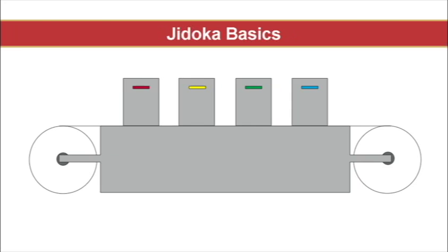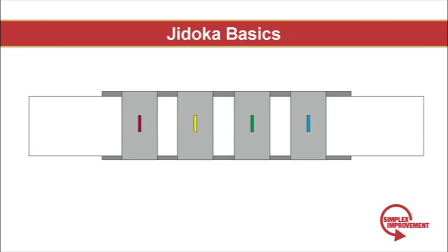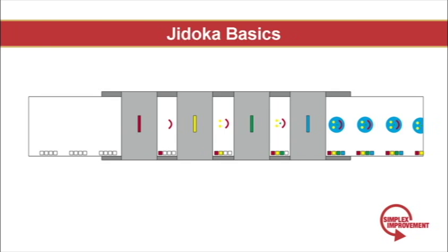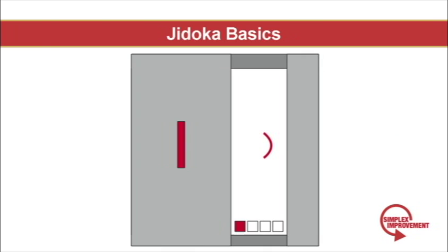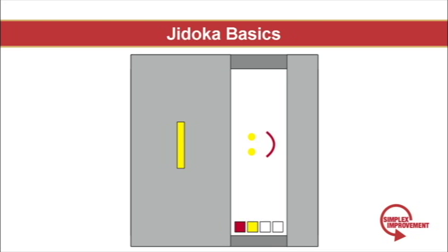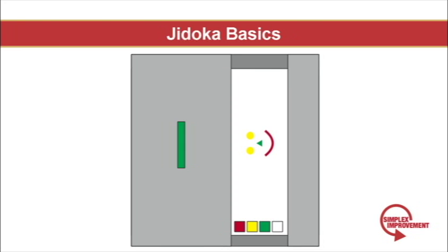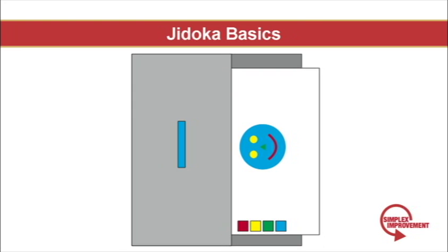Each color on this box is printed one at a time. Each tower on a printing press is loaded with that particular color ink. Once the paper makes it through the entire press, the image is complete. Each time the image passes through the tower, it also prints a small square of the same color on the edge of the sheet. If the squares line up, it means the image is in spec.